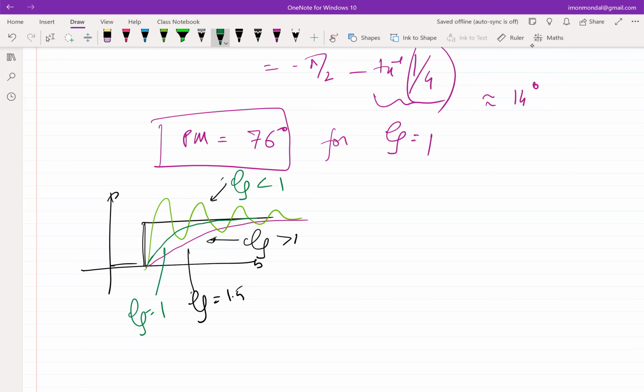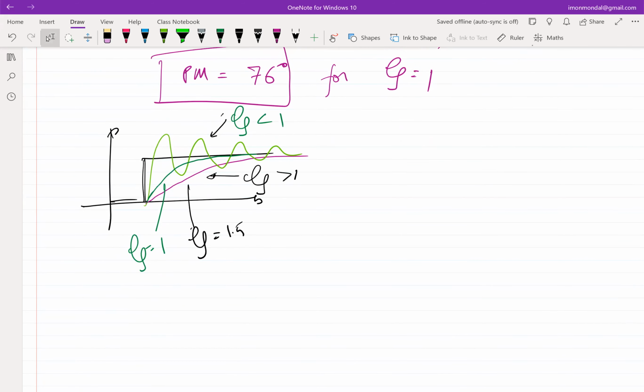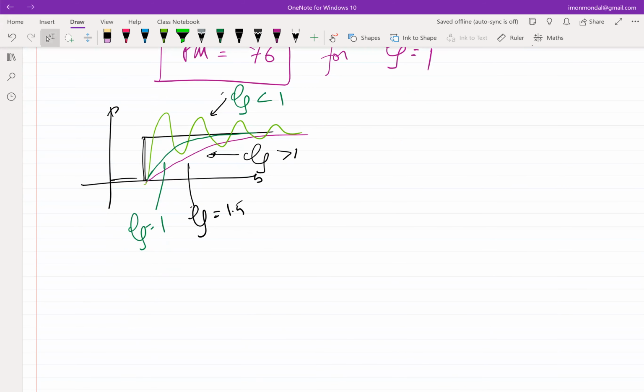Yeah, even with 1 by root 2, it overshoots. In frequency response, it doesn't. In time domain, it does. That's the Butterworth approximation. The step response of Butterworth rings. So what you are talking about is maximally flat frequency response, I think.